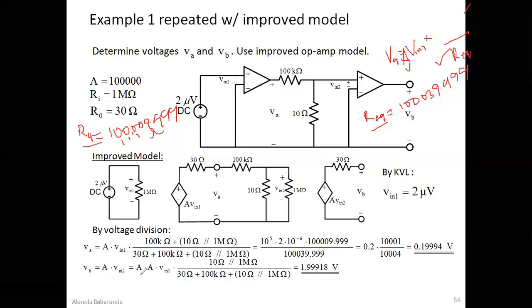I don't want you to get confused with what is here, so I'm going to show you. V_in2 will be equal to R_in2 divided by R_equivalent multiplied by the voltage source. Again, you're going to use voltage division to fix that. Normally V_in will just be equal to the voltage source; for this V_in, the source will now be VA.